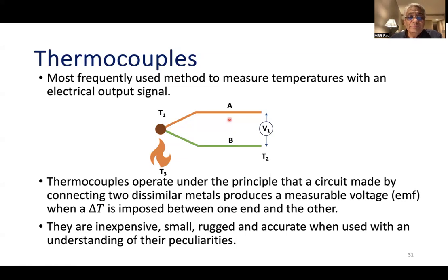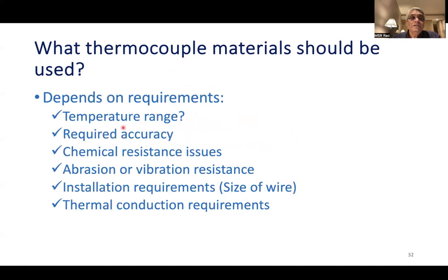And that's a key for making a thermocouple. The work functions of any two metals are different, of course. That's the reason why we start with two dissimilar metals, so that the current flow in each of those arms or legs is different when the junction is heated, and that results in a voltage being developed there.